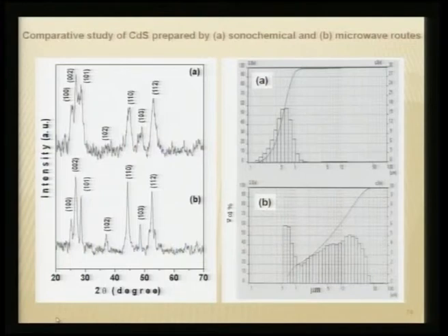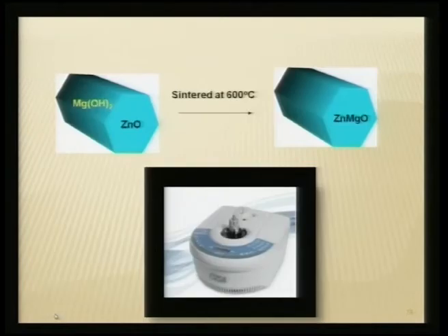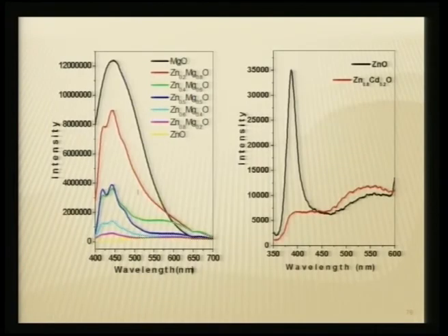So with the last slide that I want to show you: I have shown in the last 2 lectures how quantum effects can be governed by different chemical routes, and I have also shown in today's lecture how the microwave polyol route can be used to understand the alloying effect and its influence on PL, and also how the combustion route can help in preparing these compounds. So the wet chemistry route seems to have a lot of consequence on the photoluminescent properties of these wide band gap semiconductors.